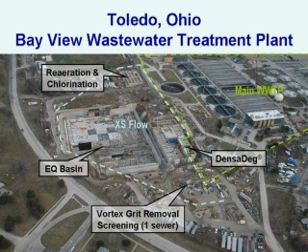ActiFlo. The slower startup of DensaDeg takes longer to come online and get up to a level of performance that has effective solids removal, and that was not as much of an issue in the city of Toledo because the process is followed by either flow going into the secondary process of the plant or by going into the equalization. So that was not a critical issue in the case of Toledo.